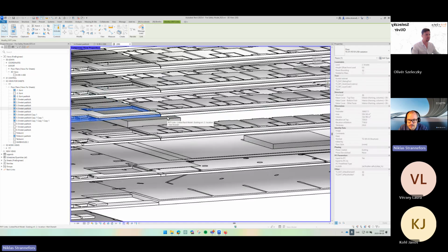I also can see if I select these different ones, we can directly see here in properties, thickness. It's grayed out because it's a linked object, so everything's always going to be gray. But the thickness here, we will see it in a second. It's called a reporting parameter. So it just reports how the floor is built up, and it will showcase that thickness.